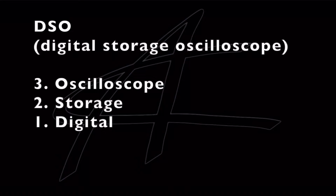And we're talking about new and digital versus old and analog. Do you need the digital functions? Do you need extremely fast rise time? Do you need 2 gigahertz of bandwidth? Do you need digital logic and decoding, or do you have a logic probe? Do you need the digital multimeter functions, or do you have a digital multimeter? Do you need to interface it with other digital gear and dump the information into some kind of format that makes charts and graphs, and you can export to programs and things like that? If the answer is no and you just need to see waveforms, well, then you really cut into some of the benefits that I perceive to be advantages of the digital scope. If you just need to see the squiggly lines, it doesn't matter.